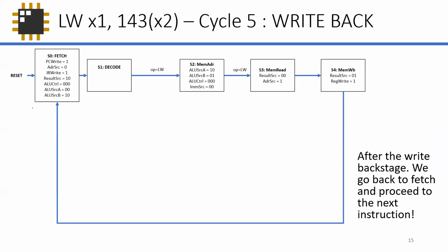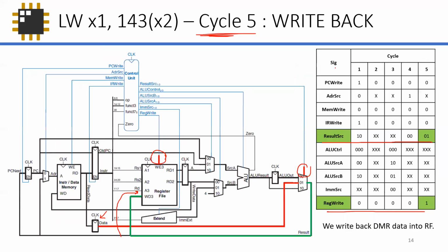Hey, how are we gonna do this state diagram that we need? Okay, so it's pretty much simple, right? And the very useful method here is the use of the table that we made last week. Use the table, highlight the important signals, assume all other signals that are not important as zeros or don't cares. And then you can eventually make the entire state diagram.